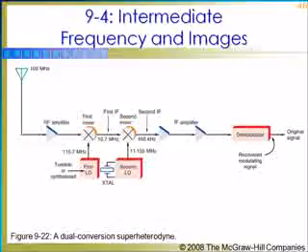So the first LO is the one that provides the tuning for the receiver, while the second is the one fixed in frequency. Since this dual conversion heterodyne needs to convert only one fixed IF to a lower IF, this local oscillator does not have to be tunable.